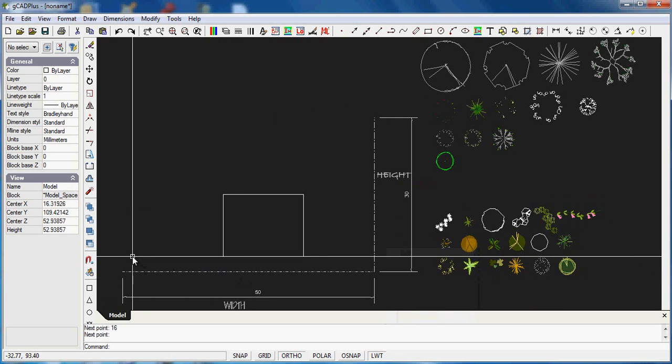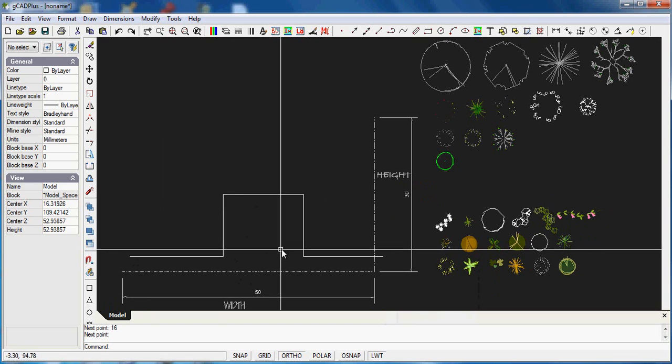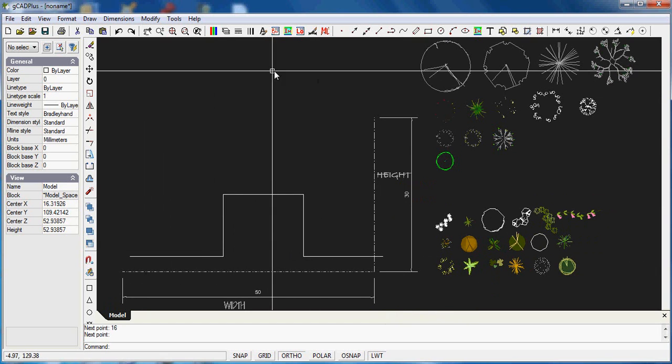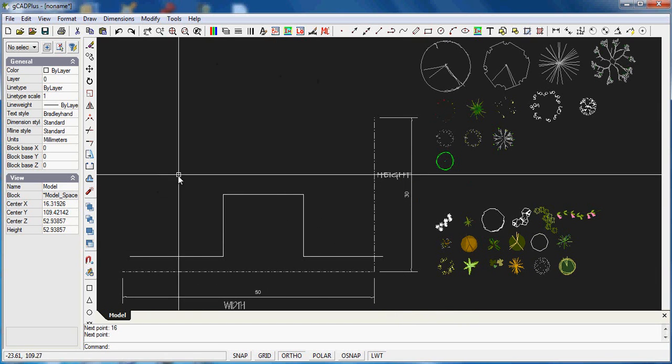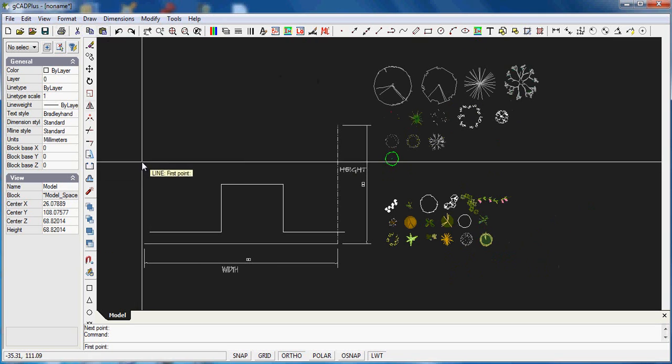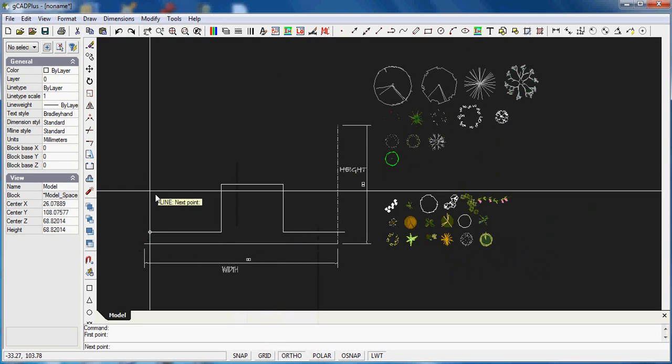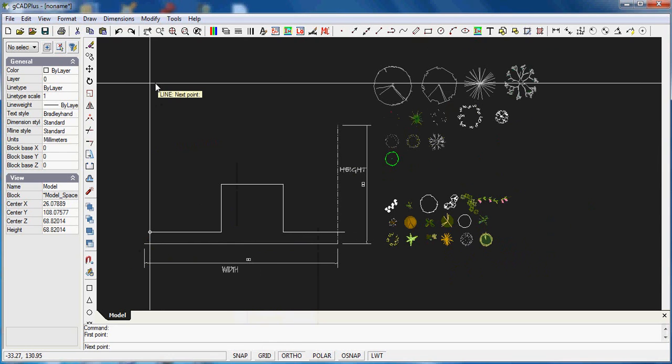Now we need to draw, and this might represent the footprint of the house. This might be a glass enclosed room and you're looking out onto the garden space, which might stretch out here. So we'll just zoom out a little and we'll draw in some more lines. So we draw a line, and I'll right click and say I'm going to jump to the end point of that line, and we'll head off here. We'll say 45 feet in that direction.